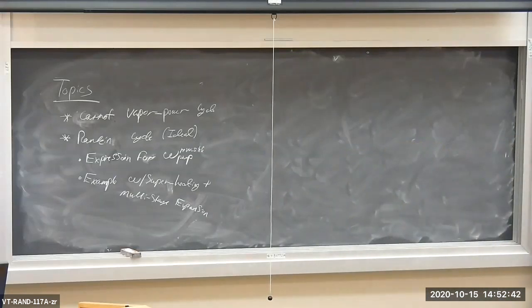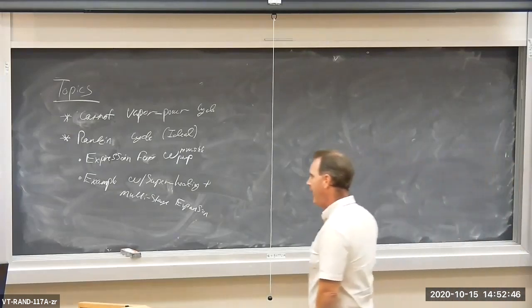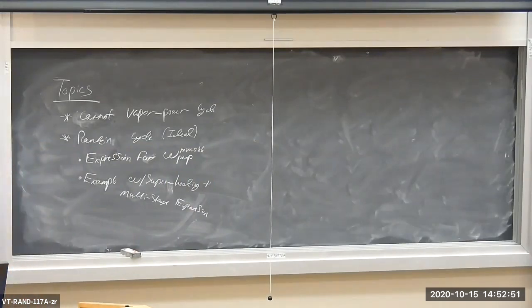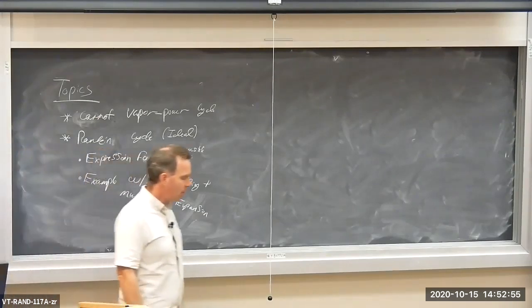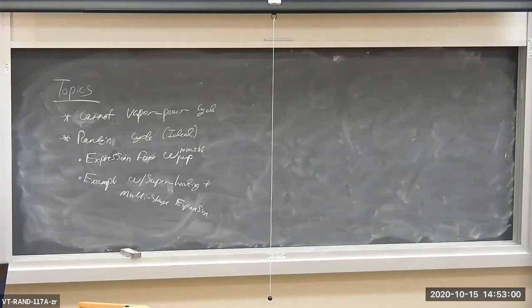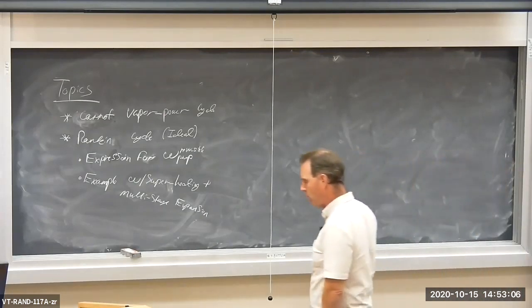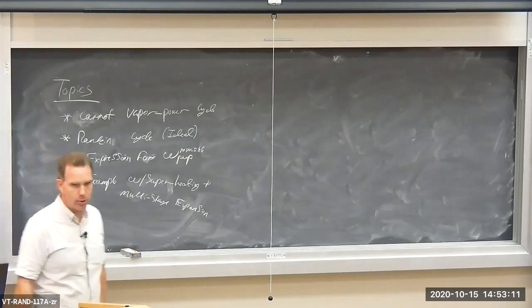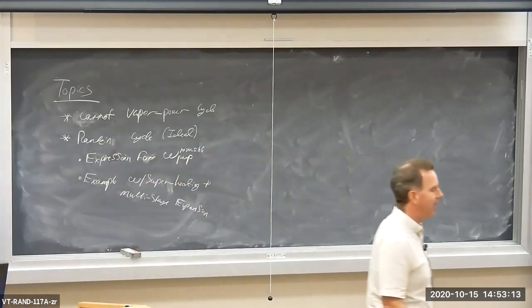So we're going to take a Carnot cycle, which is operating inside the saturation dome, and we're going to produce the Rankine cycle after we modify it. Okay? Now, a new device is going to crop up when we have the Rankine cycle. Instead of having a compressor compressing H2O, we're going to have a pump. What's the difference between a pump and a compressor? Well, pumps raise the pressure of a liquid, and compressors raise the pressure of a gas.